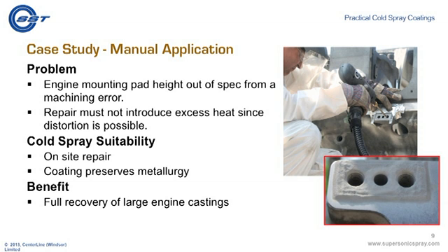This is an example of an SST field service where we actually put one of our SST technicians at the customer's site. So it was an on-site repair. The application went very well. You can see the three-hole engine mount there has a fair amount of nickel coating applied to it. The customer would just put this back through his normal operations and finish it to his correct tolerance.